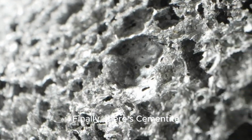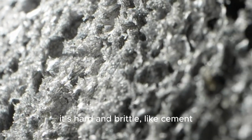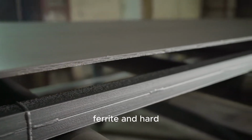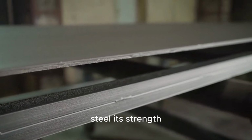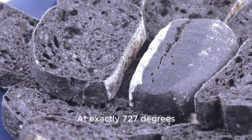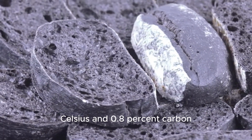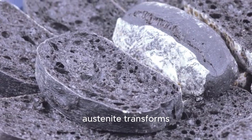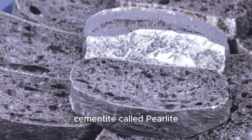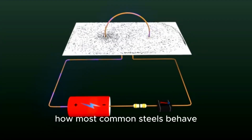Finally, there's cementite, or iron carbide. As its name suggests, it's hard and brittle, like cement. The balance between soft ferrite and hard cementite is what gives steel its strength. A crucial spot on this map is the eutectoid point. At exactly 727 degrees Celsius and 0.8% carbon, something special happens. Austenite transforms directly into a layered structure of ferrite and cementite, called pearlite. This point is the foundation for understanding how most common steels behave.